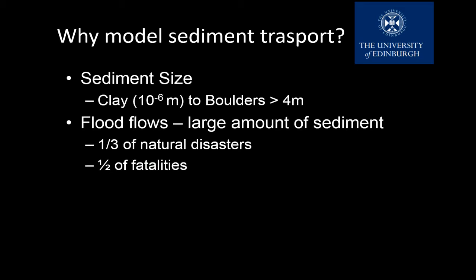And one of the things that I've been looking at in my PhD is flood risk modelling floods, dam breaks especially. And what happens when you have a flood is that you have an increase in the velocity of the flow. And so this increase in the velocity causes these sediment particles to be either entrained into suspension and then carried with the flow, or else rolled along the bed, depending on the velocities of the flow and depending on the size of the sediment particles.